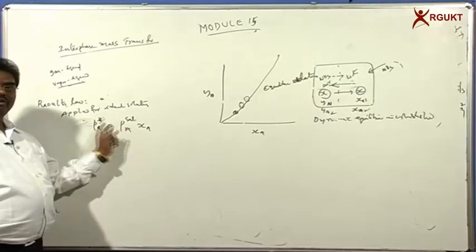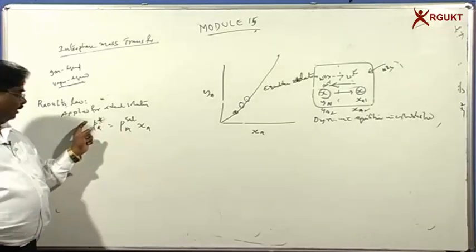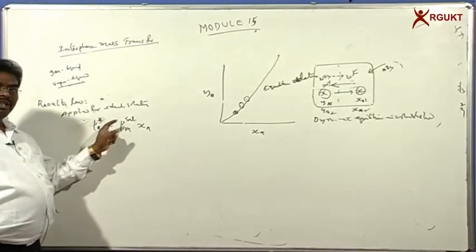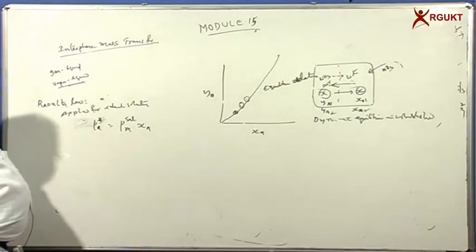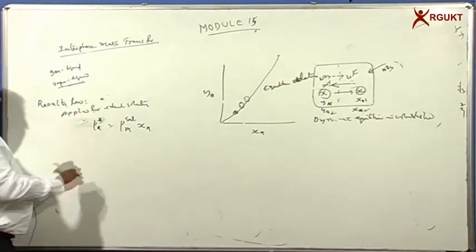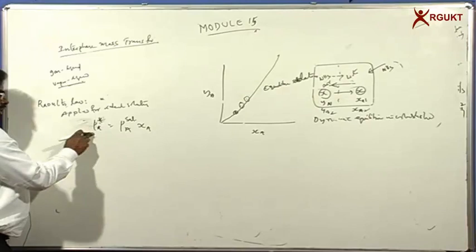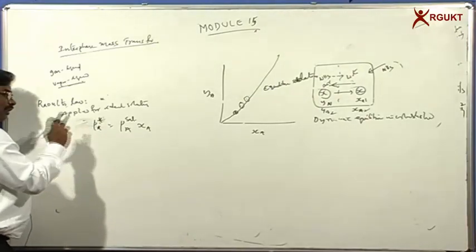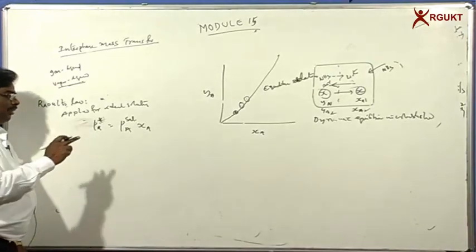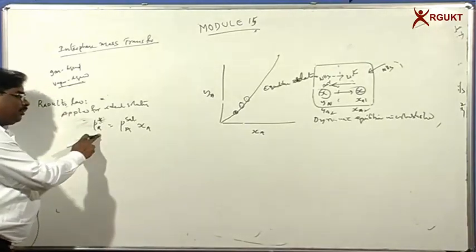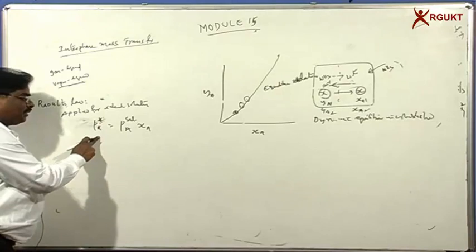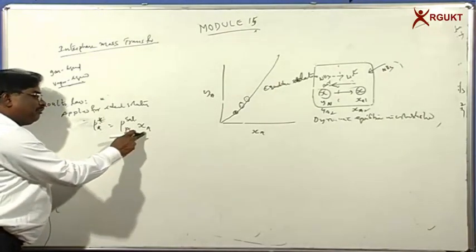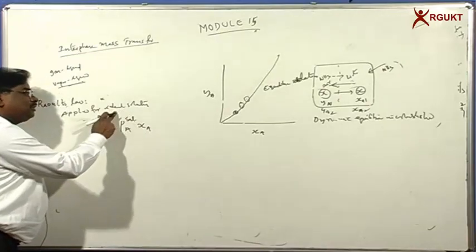This holds if the vapor phase and liquid phase are at equilibrium. So one can use this equation to estimate the partial pressure of a component in the vapor phase, because the vapor phase will not contain only one component, it contains a mixture of components. So the partial pressure of component A in a mixture is equal to the saturation vapor pressure multiplied by the liquid phase mole fraction, if the solution is an ideal solution.